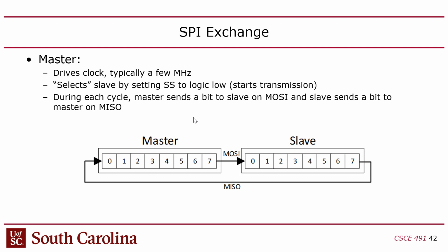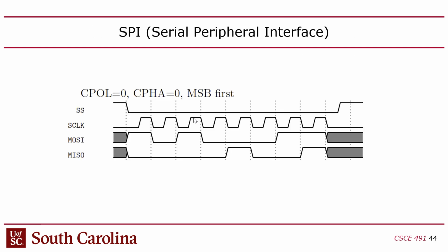And then we looked at some timing diagrams. So I think you guys told me last time you've seen these before. One of the reasons I cover this is to understand interfacing, but also it's great practice to be able to read these timing diagrams, because these are pretty common whenever you have hardware communicating with each other. So you've got here the horizontal axis is time, and then you've got the 4 signals that are laid out vertically, and each of these signals is a single bit, so they can be high or low, right? Dotted lines represent moments of time, instants of time, snapshots of time, right?